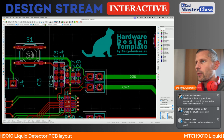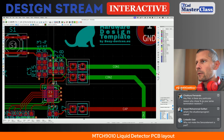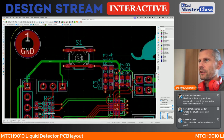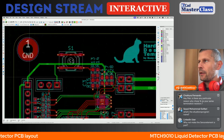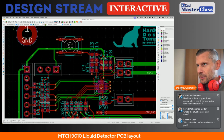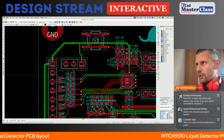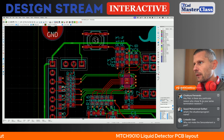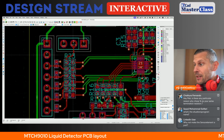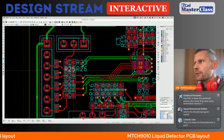So it will take a while until I place all the reference designator labels. I'm removing the obvious reference designators. I don't need the reference designator for the header because I will use labels for each header pin. I don't need designators for diodes. I will use the designators for the resistors.